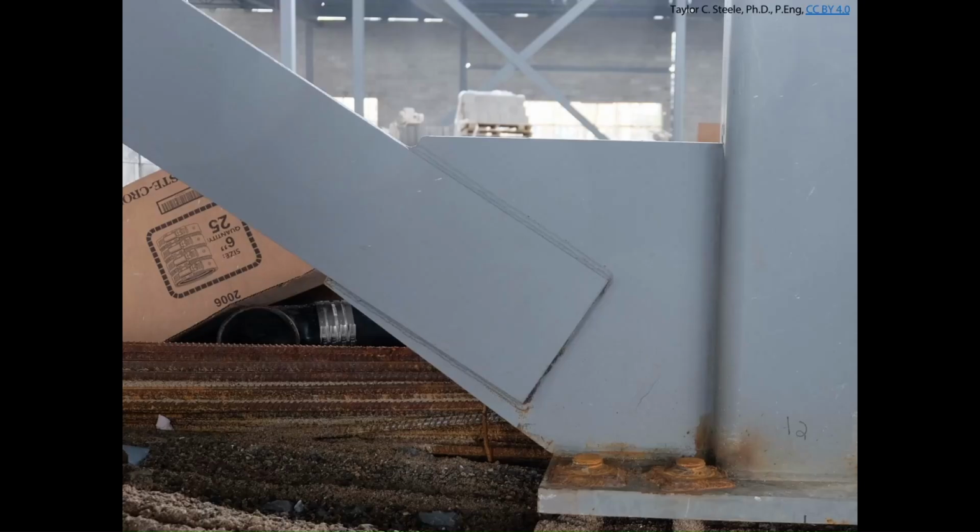And here you can actually see, just at the bottom here, this is where that angle clip was, and that's where the weld that they had to grind away was. They had pre-tensioned everything here. And it's pretty clear to me, anyway, that you can see there are at least two beads of weld here. Generally, we can only build up a certain amount of weld by running the electrode in a single pass. A lot of times it's going to take multiple passes to build up a weld that's big enough for us to have enough resistance through that weld metal that we can transfer the tension force to the gusset plate.